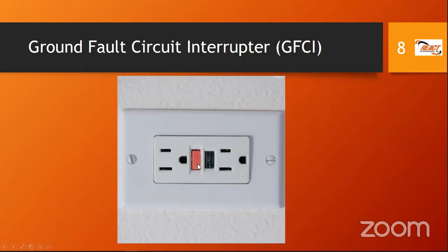So this provides additional safety in case maybe the insulation isn't so good on the appliance, maybe using a kettle, maybe using a drill, and you don't want a human body coming into contact with a live system and getting shocked or suffering an electric shock. So the GFCI can detect that stray current and trip, and therefore kill the supply to the device. So that's the purpose, the reason why we use GFCIs like these. You might have seen them around, and it's simply ground fault circuit interrupter, GFCI, or ground fault interrupter.